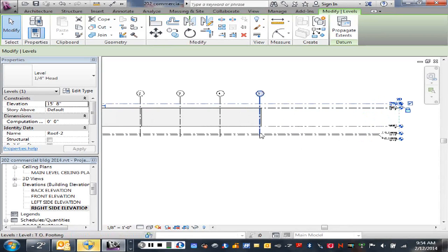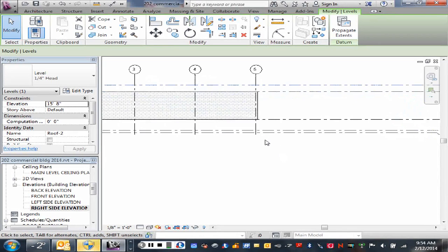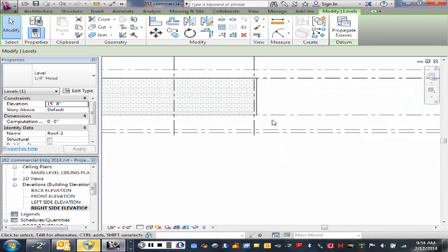Okay, let's go down then from this level down. We talked about putting a basement in this building. And if we put a basement in this building, it's commercial construction, so one option would be to go with bar joists and beams and put a metal deck on that and then pour a concrete floor on top of that. That's one option. The other option is to go with precast concrete planks. You all familiar with precast concrete planks? Probably talked about that in your methods and materials class a little bit. Okay, so we're gonna opt for that.